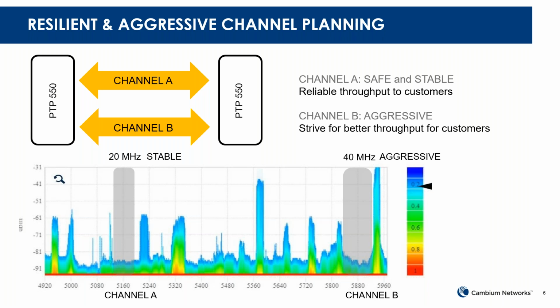I have one more question: aside from the integrated antenna, is there any specific dish for high noise interference environments? Generally speaking, as I said, we only offer the radio with antenna, but technically there is no proprietary interface there. Almost all 5 GHz antennas use N-type connectors.